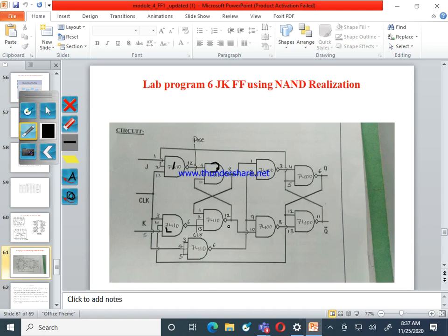Okay. Can I move on to the down one, the fourth one? Is it possible to do it in the same IC? Do you have a pin? We have a pin because in one IC 7410 I can realize a maximum of 3 NAND gates. Then 1, 2, 3 is over.